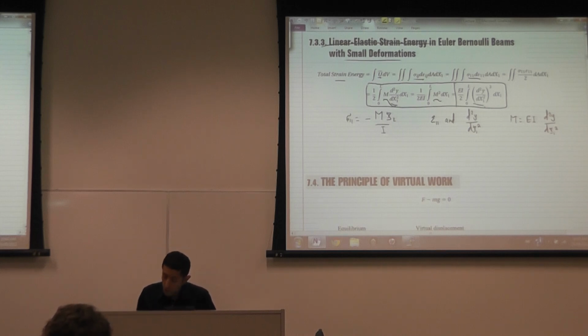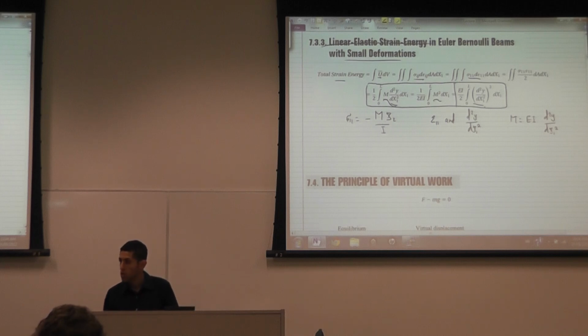I started with sigma 11 epsilon 1, integrated, and replaced the stress and the strain with functions of the moments and the second derivative of the displacement, and reached this equation in terms of the moment rather than in terms of the stresses. You could do it in terms of the stresses, but we only deal with moments and y.